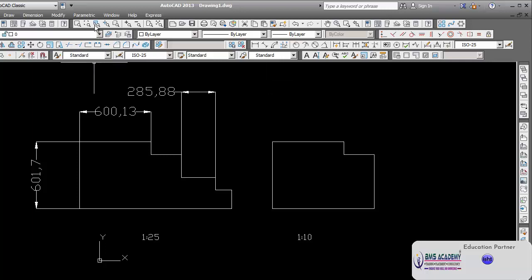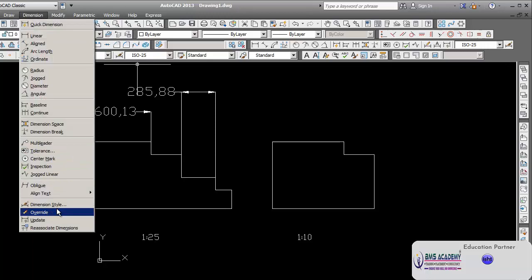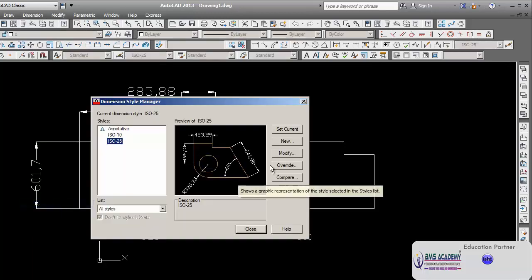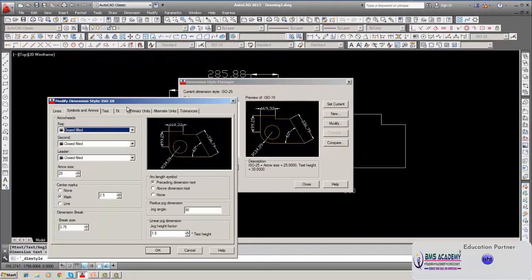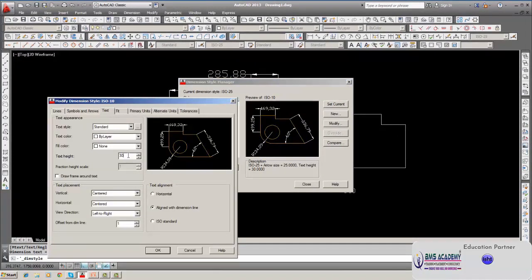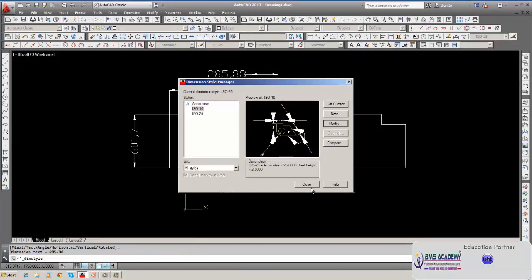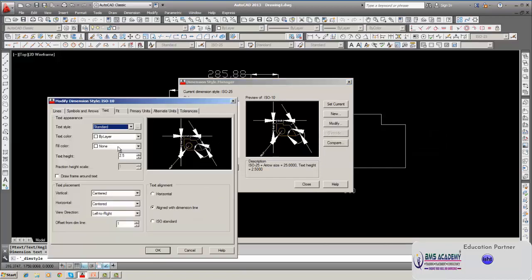So it is not adjustable. You will have different sizes of letters, and so to make it uniform, you can have the same thing. I will just show you. What are the properties here? Text is 30, it is there, I will make it 2.5. So that same height will remain. 25 I have to make it, not 2.5.